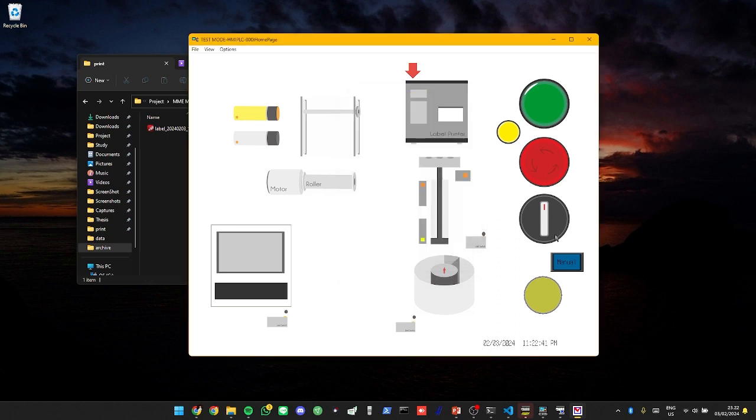Okay, so when we try to run the sequence, it should be in automatic mode, and then the box itself should be inputted into the scanner box, so the limit should turn on. And then this one is for the label printer, so whenever the printer has already printed out the label, the roller in here will come down, and the sensor will sense that the roller has already come down.